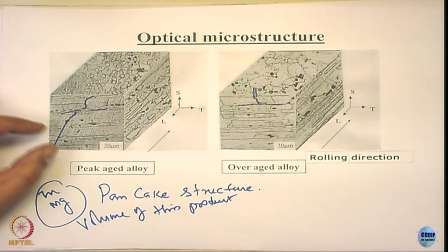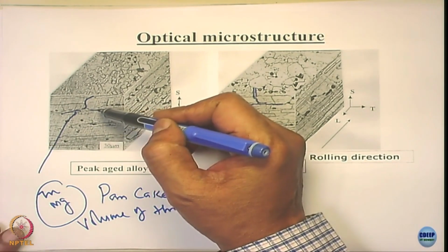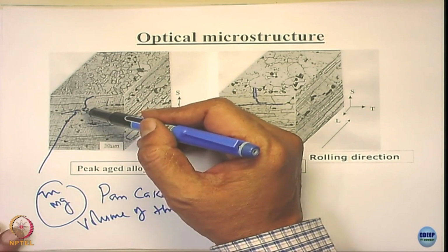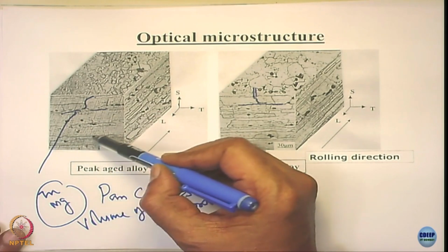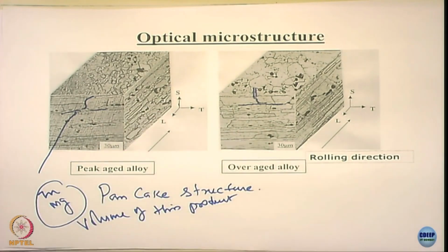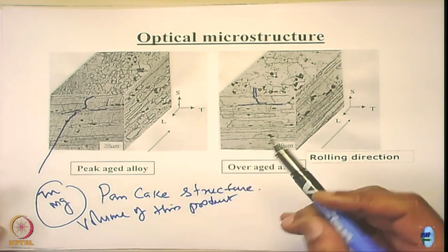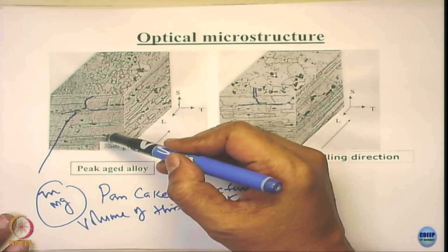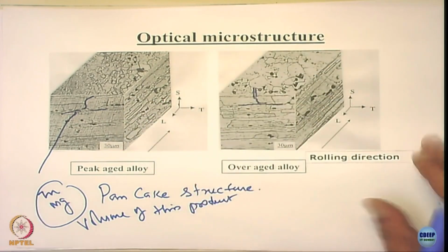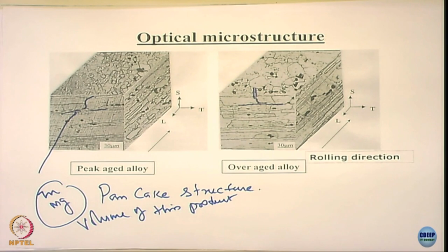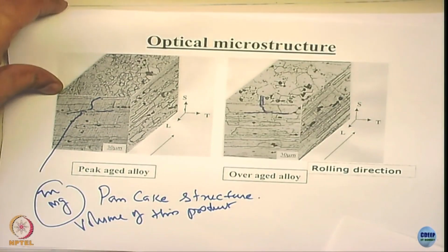In addition to corrosion happening because of preferential dissolution of the grain boundary precipitates, it is also going to exert certain stresses, and so there is going to be delamination along the grain boundaries. The grains start lifting from the material below the subsurface. So it exfoliates, they delaminate actually. So that is what really happens in the case of these materials. If you want to see how it happens, I can show you a diagram of how this happens.